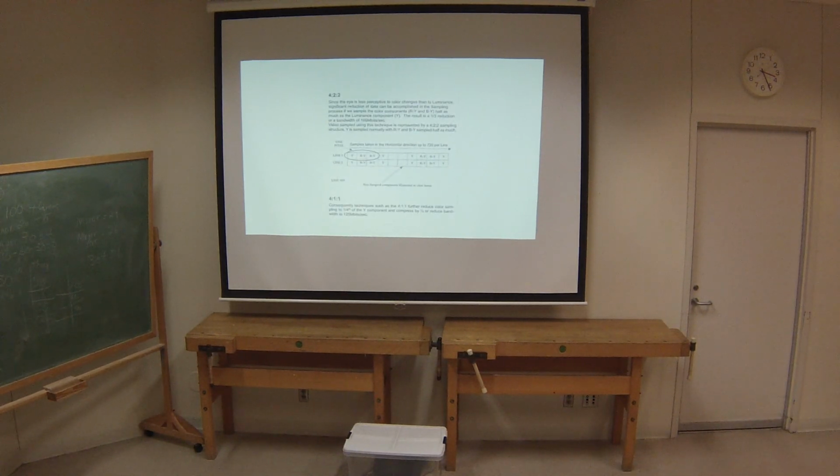Now, let's consider what happens at the local TV station. Even in the days before HD, the TV station recorded in what was referred to as 422 video. Basically what that means is that for every 4 samples of Y, so here's a sample, here's a sample, here's a sample, and here's a sample, they only took 2 samples of B minus Y, R minus Y. What happened to the other 2 color samples?